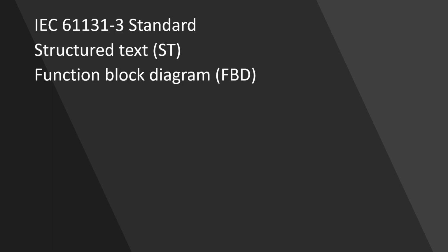It's easy to learn and use, and fast to some degree. Fast to learn, not super fast as a program, but yeah. You can even use custom function blocks that have ST written in them. That's useful when you have a very complicated program. You might want to make a custom ST function block.